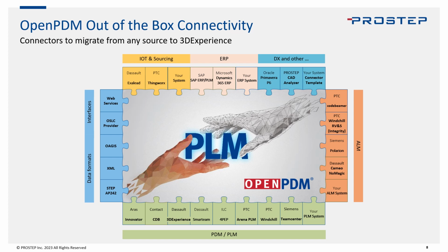Not just for generating the geometry data from CAD, but generating actually the PLM data in a CAD format and then merging that with geometry that might have been created from the CAD export from the CAD system itself. So we can use a LOTAR type of process with our STEP toolkit in order to archive data efficiently.